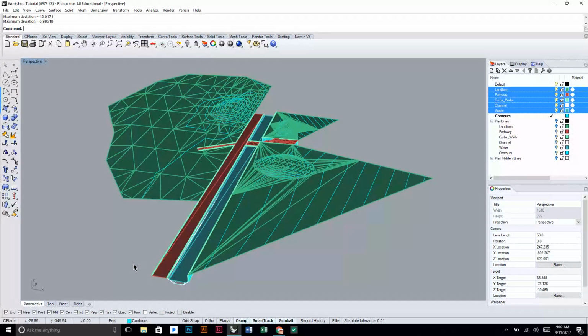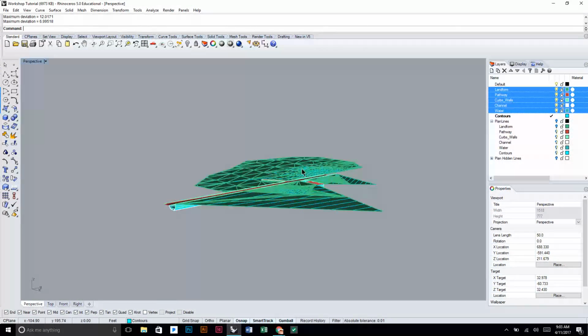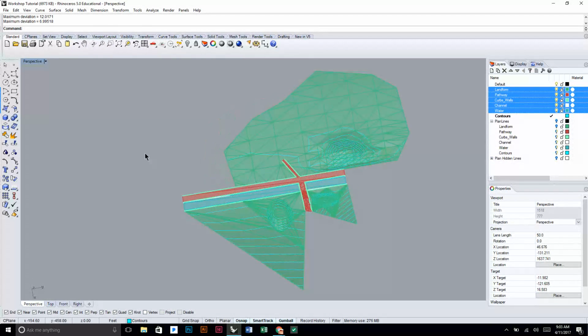For a section, we have vertical cutting planes. For the floor plan, we'll have a horizontal cutting plane. Same exact fundamentals. Because they're very similar, I'm just going to show one, in this case, the section plane cuts. You could use that approach of using a contour and tell it to create contours this way, and then you can physically cut away your objects, which may or may not be good.